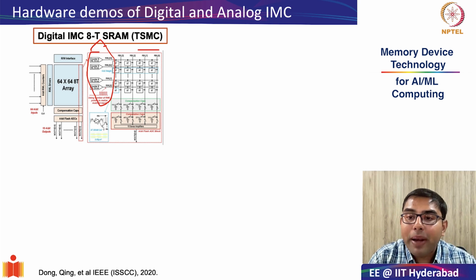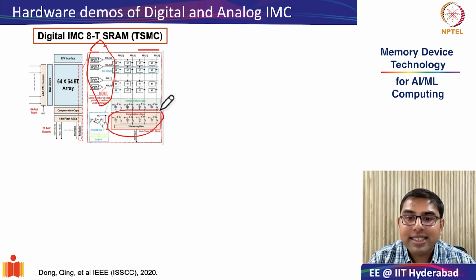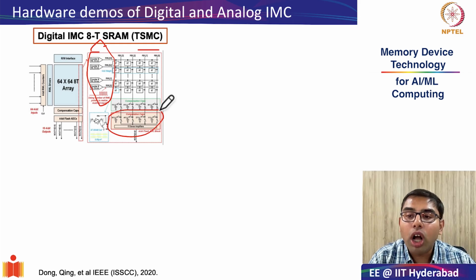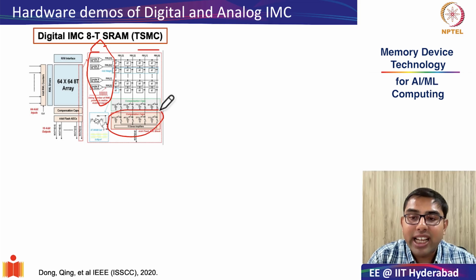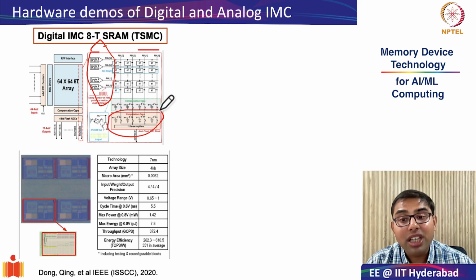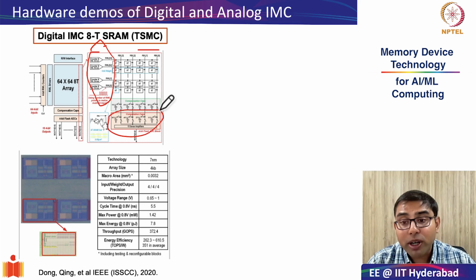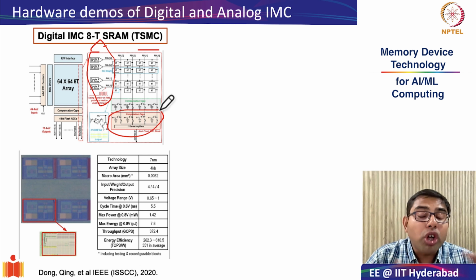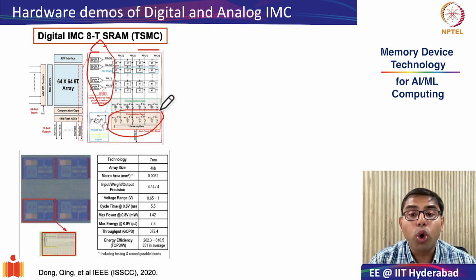A post-sampling charge sharing step among the binary weighted capacitors produces the final analog MAC level, which is digitized by a 4-bit flash ADC. And with this, the authors explicitly model device-to-device nonlinearity using better neural network training, improving the MNIST accuracy by almost 30%, and it shows very good convergence to software levels with just 4-bit precision.